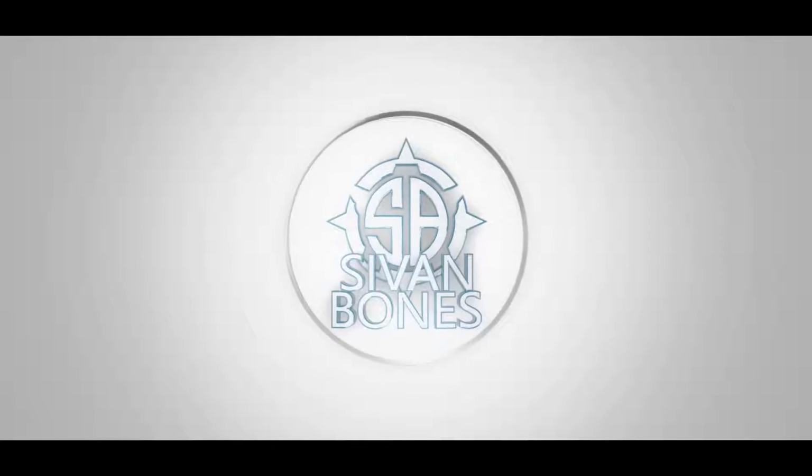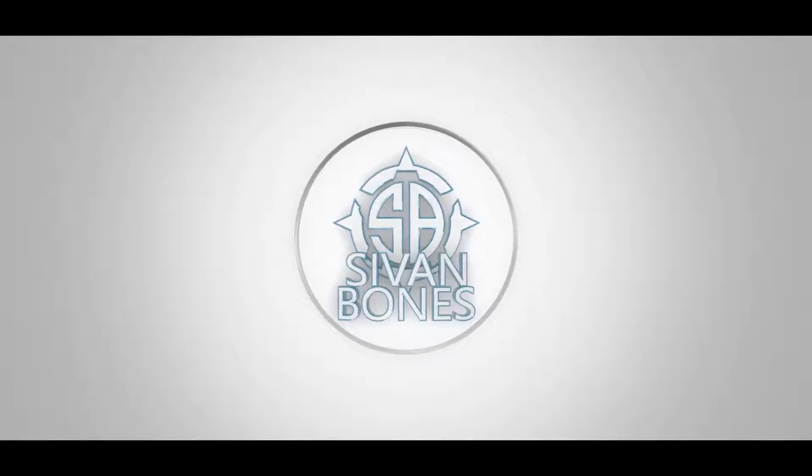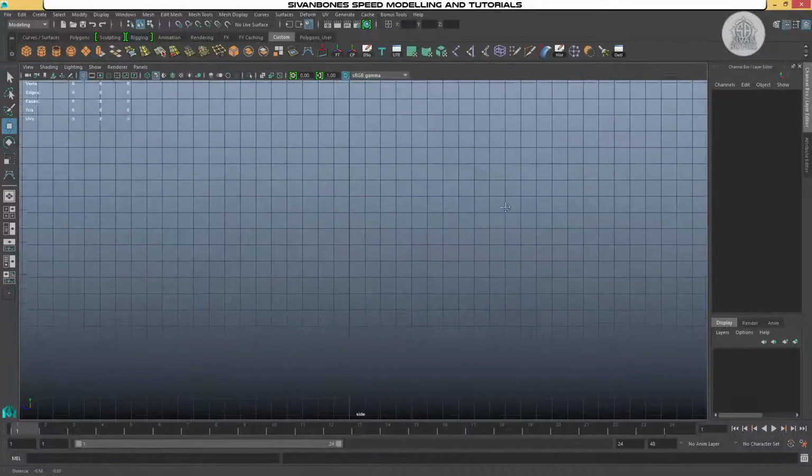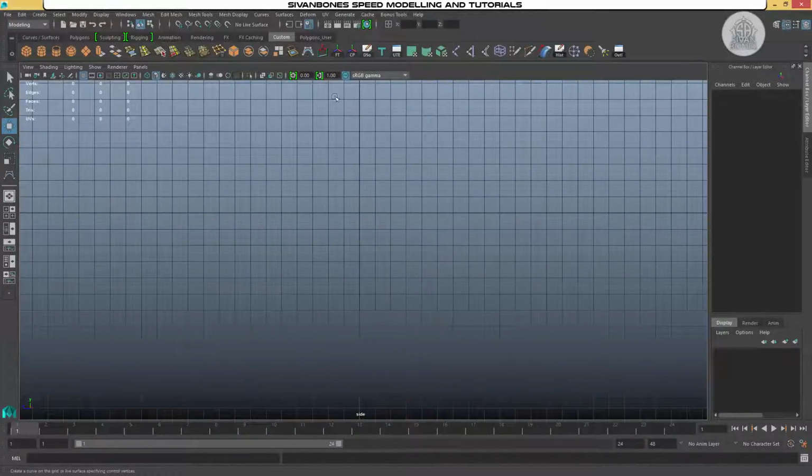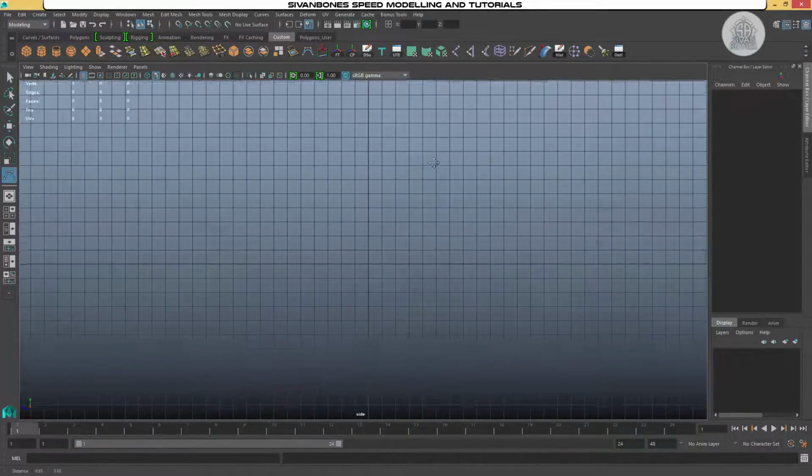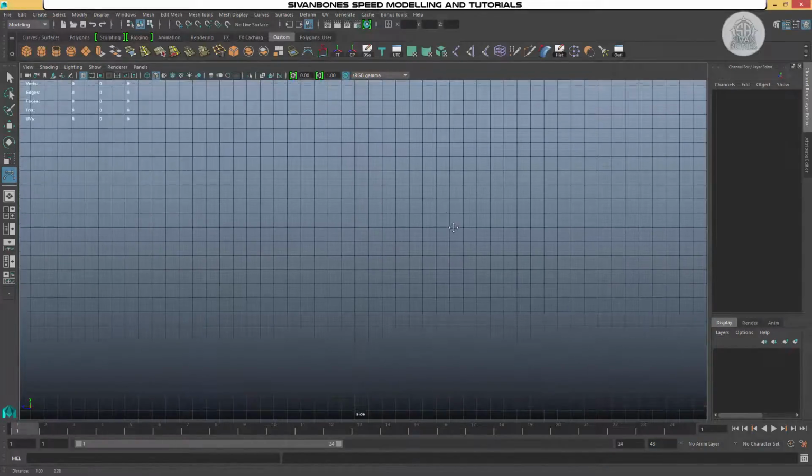Hey, Sivan here. In this video we're going to be looking at the CV curve tool and we're going to combine it with the Revolve tool. So what we want to do, same as previous videos, we need to make ourselves a curve, but this time we need to make a very specific shape with our curve.